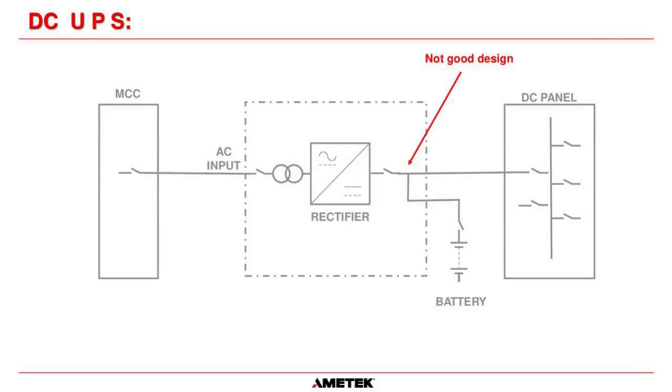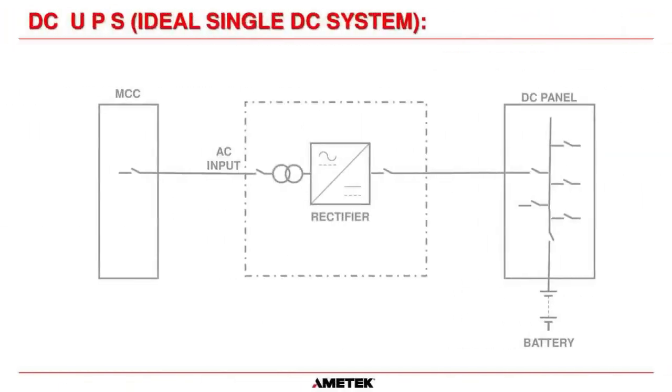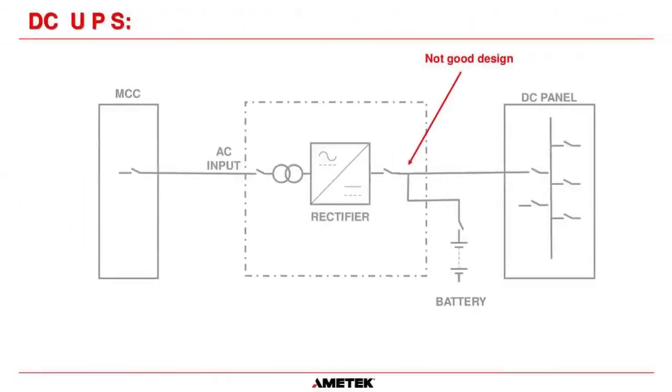So what's not a good design? Well, a lot of people will look at this drawing here and say, well, there's not much difference between what I'm saying is a good system design and this one here where it's saying not a good design. The difference in this one here is they haven't connected the battery directly onto the DC bus inside the DC panel. What some people do is they actually connect the load cables and the battery cables to the output terminals of the charger.